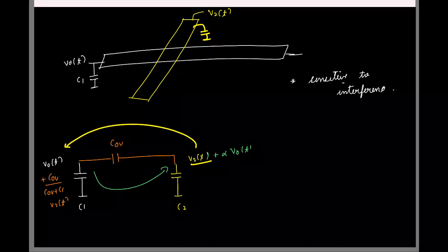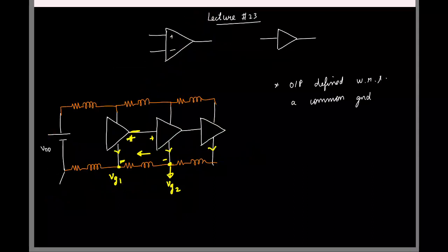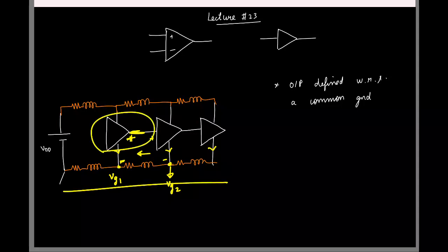Okay. So the solution to all these problems is straightforward. So if you think about it, the initial problems we have is because our output signal is defined as a potential difference between one line which is local to our block and one other line which is common to all the blocks. Because that second line is common to all the blocks, everyone is coming and dumping their garbage and disturbing it.